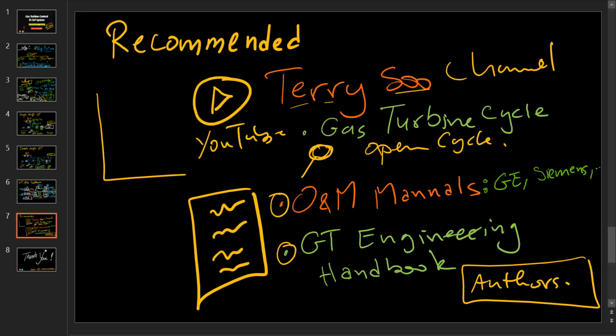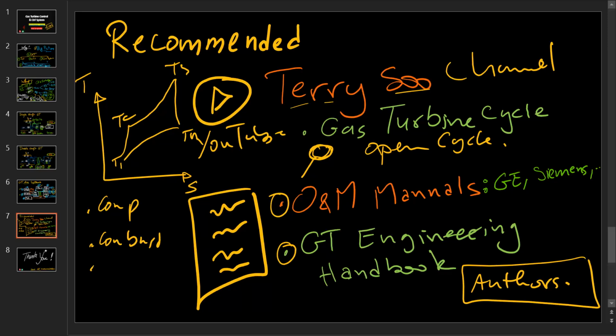Because it's really animated and it shows the different Brayton cycles on gas turbines, thermodynamic ones, where you can see temperature versus entropy, and you will see the cycle of getting from T1 to T2 to T3 to T4, and you will get to know gas turbine compression, combustion, and expansion relations.